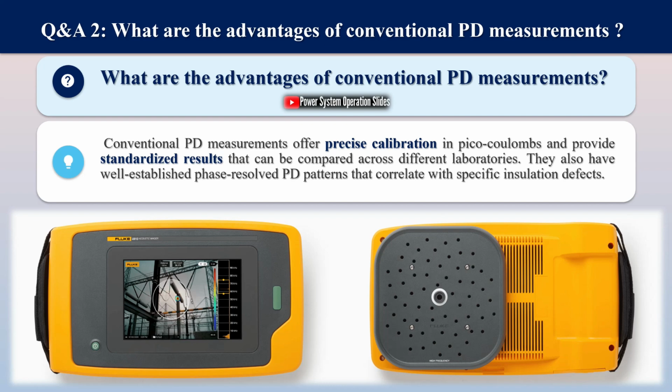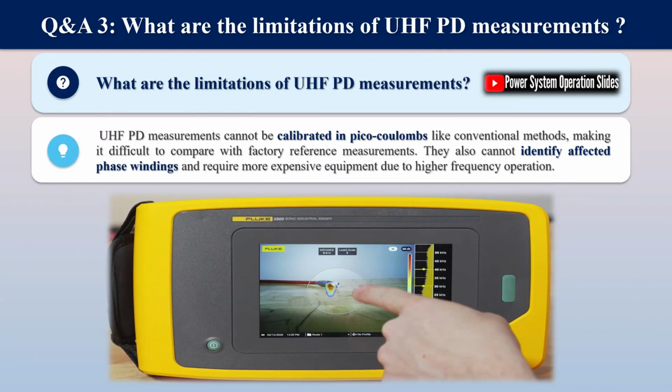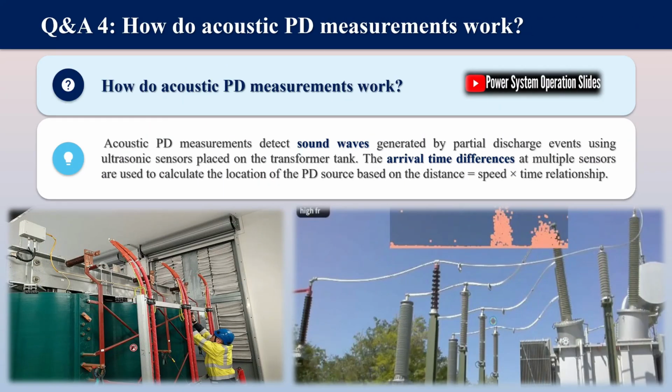The signal sensitivity of acoustic monitoring varies significantly based on the specific system and installation, with generally detectable sources including PD outside windings, arcing or tracking of bushing surfaces in oil, PD inside tap changers, and very high-intensity discharges within windings. However, acoustic detection faces challenges with discharges within windings, inside HV bushings, and signals produced by gas bubbles, which are typically difficult to detect.